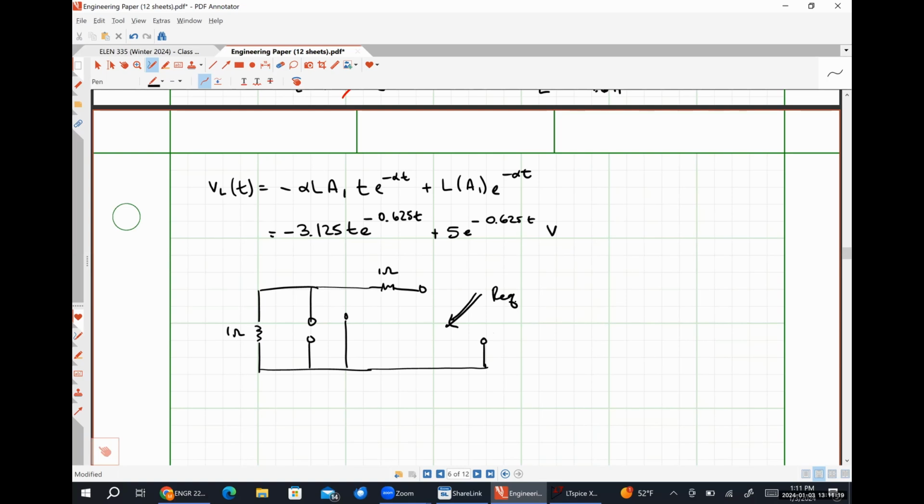So that is the process always, always, always for finding the equivalent resistance in these circuits. We take the energy storage elements out. So they need to either directly be connected in series or directly connected in parallel. Look in through the terminals that are left behind with a dead network.